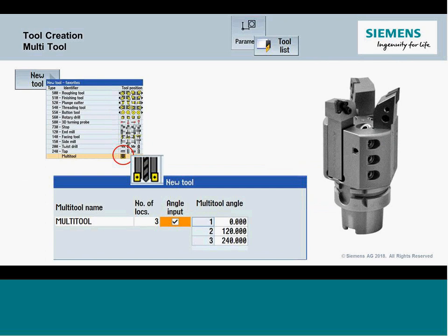When you get to this more advanced technology, of course, you kind of do more things. So there are some new tools that become available to you in this technology range. And one of the tools that's pretty neat is what we call a multi-tool. Multi-tool allows you to have a single tool location, but it can handle multiple types of configurations. So here on the image on the right, you've got a holder, and it's holding 2 different types of turning tools, probably a roughing and a finishing tool, and it's even holding a threading tool.